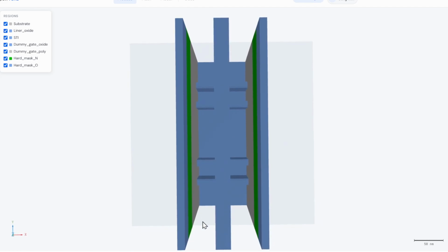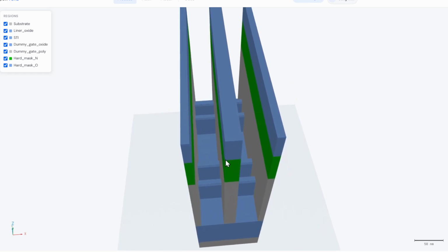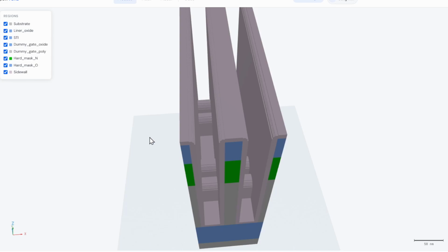So now from the top view, this is the dummy gate, and this is another dummy gate, and between gate and gate, these are places for our later source and drain. If we make our source and drain directly in this etched part, then actually there will be no separation between source and drain and dummy gate.